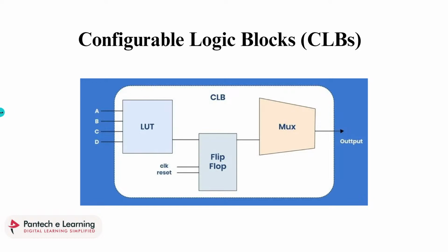First we see the lookup table. The lookup table is one of two crucial components forming the FPGA architecture. Combinational circuits like multiplexers, adders, encoders all come inside the LUT. It takes thousands of SRAM bits and multiplexers. In the lookup table we can design lots of multiplexers, thousands of decoders, adders, encoders, demultiplexers. It is fully based on how many logical elements the CLB has. If the CLB has few logical elements, we can't design too many combinational circuits like adders and full adders.